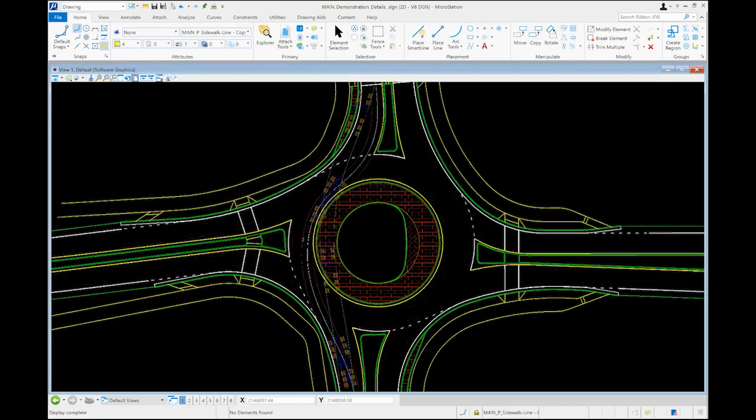And then we start getting into some oversized vehicles. For this particular site, we had a couple different oversized design vehicles. And this is where we started to get into the need for some of those outside aprons. And you can see that they're not needing that whole width all the way back to the ped crossing and the ADA ramp. It's really just requiring a little bit here in advance, but trying to provide a decent transition into that ADA ramp. And as we get along the central island, the rest of that design vehicle is being accommodated within that standard truck apron width in the southbound direction.